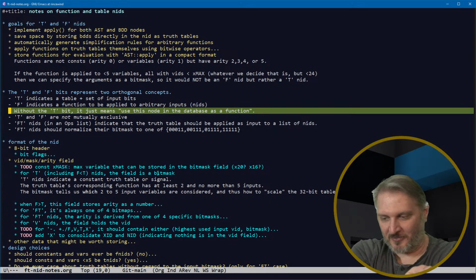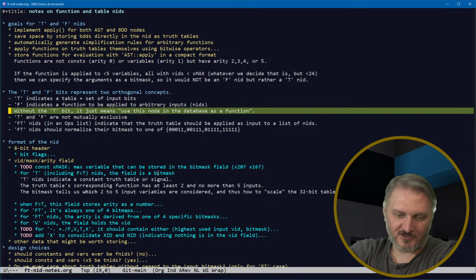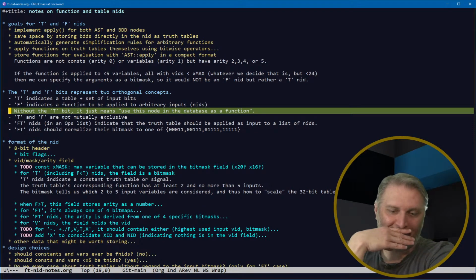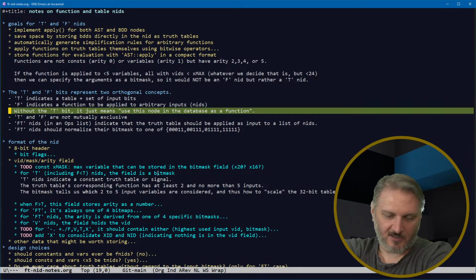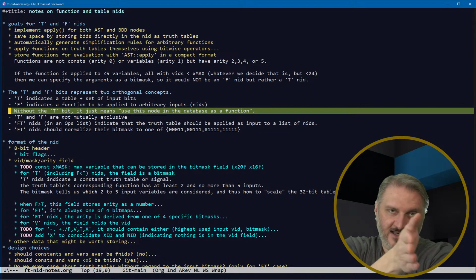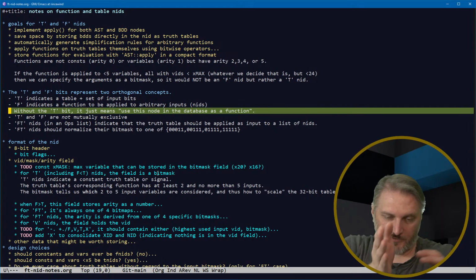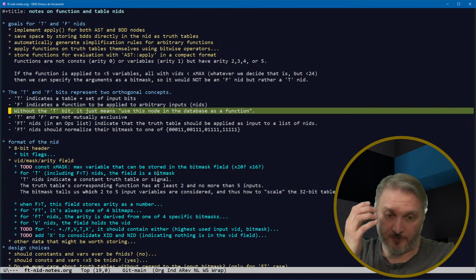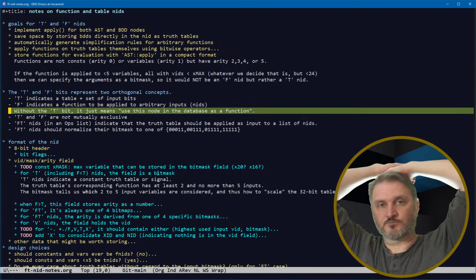So you multiply two 32-bit numbers together. The first one depends on 2, the next one depends on 4, the next one depends on 6, and so on, because everything moves right to left. And then you get to number 32, and you're depending on all 64 input bits. And then as you keep going, you've got carry bits to deal with, and so they also deal with everything to the right.